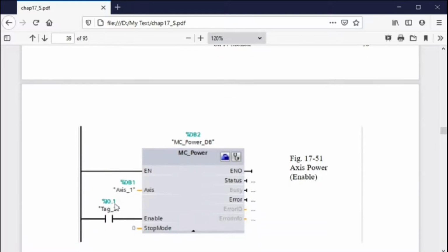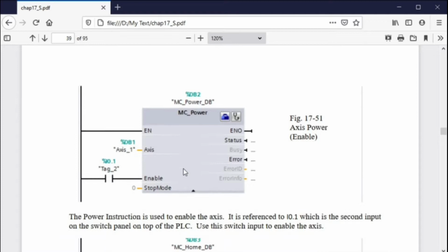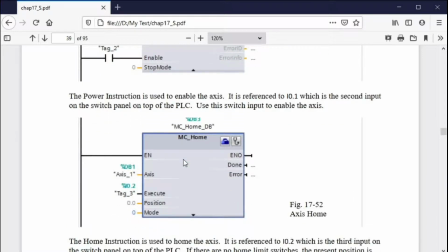The second switch is the I0.1. Then you're going to flip the power up, and it's going to turn the power on. That's your enable. So with the servo, when you hear enable, it actually starts to hum. With the stepper, you don't hear anything, but it is now enabled. So it's a nothing burger from the stepper, but from the Allen Bradley servo, you actually hear a visible hum. It's enabled, and it's holding position at that point in time, so it's working.